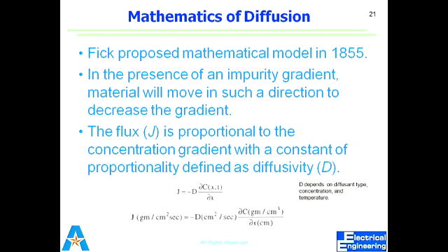After you have the surface concentration constant, that was the pre-deposition. You'll be discussing this in the next lecture; actually, I'm just giving you an idea. Then comes the drive-in. In drive-in, you put your wafer at high temperature. At high temperature, you have constant concentration on the surface, and after that, it tries to go deeper and deeper and deeper.